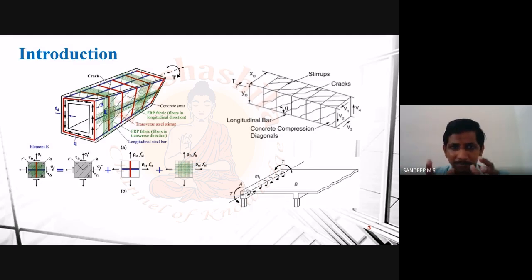Right now my question is, somewhere else we have already discussed that if the pattern of the crack is approximately 45 degrees, it is a particular type of crack, or these cracks are actually formed by dash action. What was that? Shear. It is basically due to shear. For torsion also we will observe similar patterns. If you observe from this side, you can see that it is again acting at an angle of 45 degrees. On the top side also it is at an angle of 45 degrees. This is the major difference.